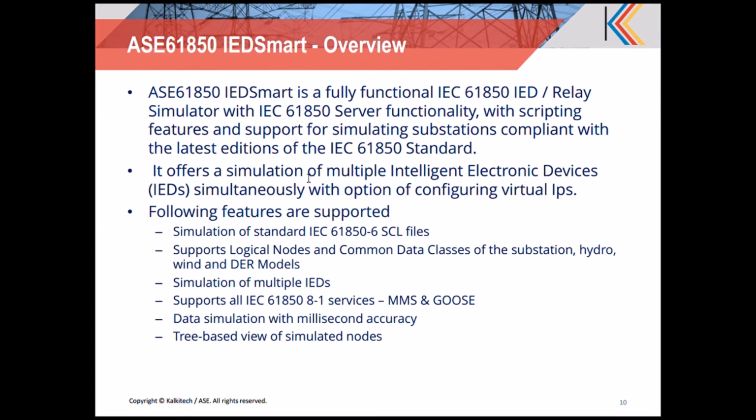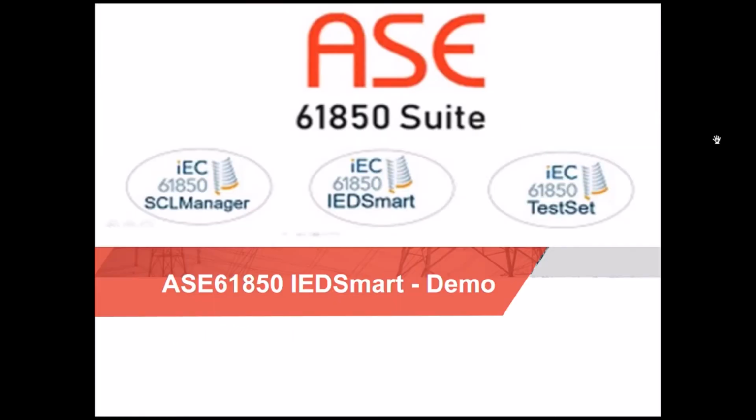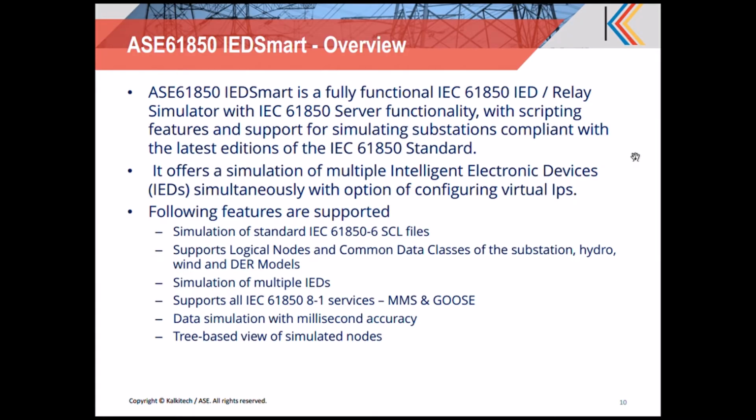It can be used to simulate multiple vendor devices, multiple IEDs, simultaneously with the option of configuring virtual IPs. So in the lab environment itself, all the IEDs can be simulated for testing purposes.